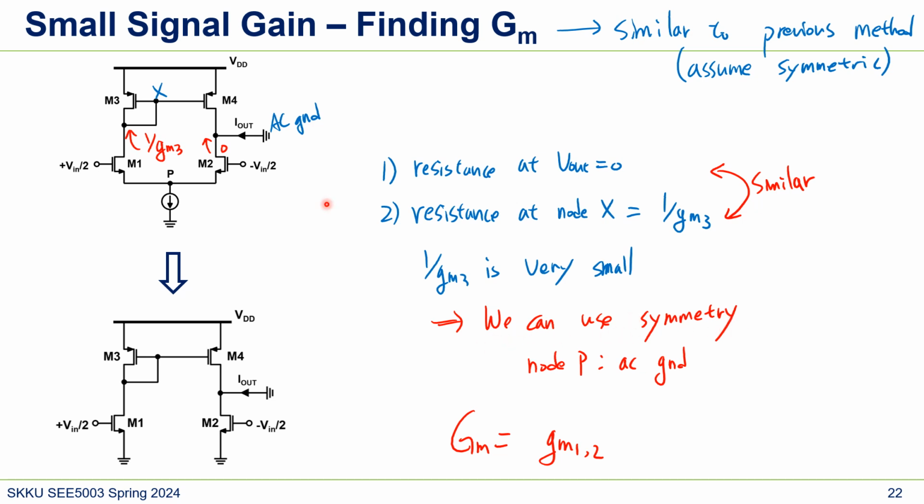So in this slide we show that by using this resistance and this finding of large GM, we can say at this stage the resistance through this way and this way are both very small, so we can approximate the circuit to be symmetric. And then we use it from here and here. That's what we calculated, right? And then we got this GM1 and 2. So we got a GM, the effective transconductance.